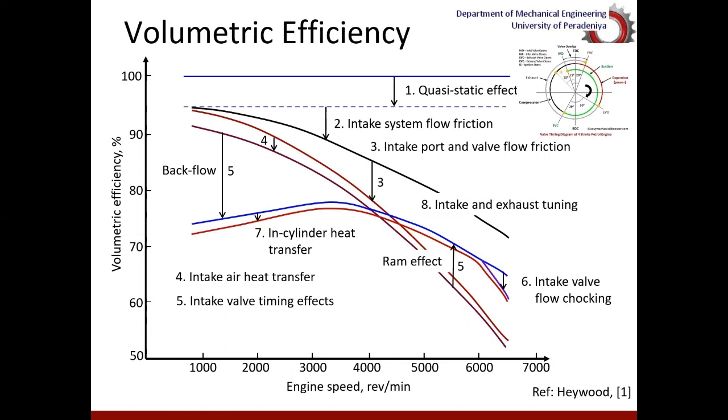Finally, as we know, exhaust and intake valve tuning enhances the flow, so the volumetric efficiency would be increased. Again, the tuning effects are more significant in the mid-speed range.